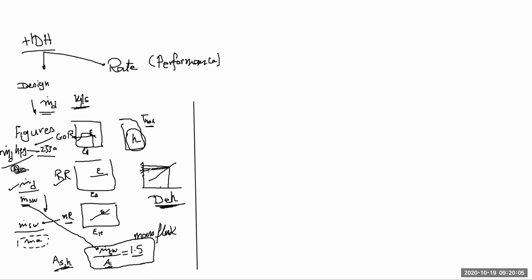So the surface area can be calculated from a figure right away, or can be calculated based on the number of transfer units and the specific heat ratio, which is the capacitance ratio. You can do this or that. It's easier to do it directly as area of the dehumidifier based on this. Otherwise, the number of transfer units is the overall heat transfer coefficient multiplied by the area divided by C min. What is C min? This is basically m dot Cp minimum.